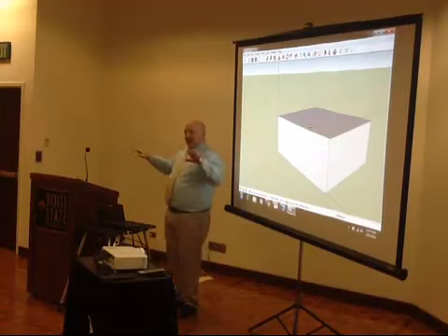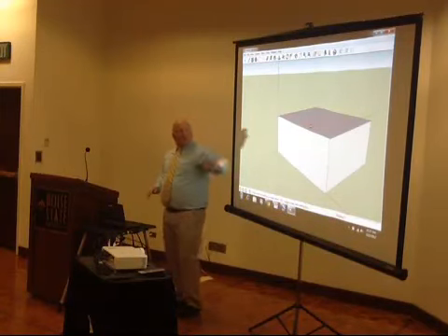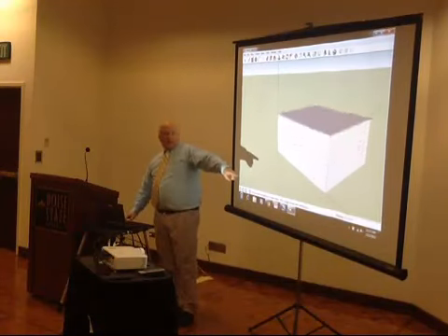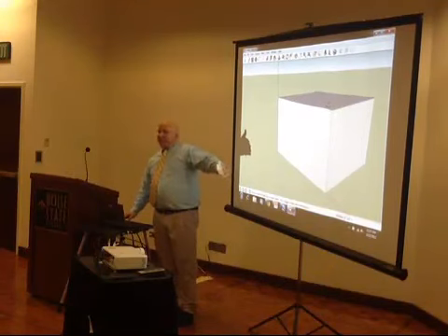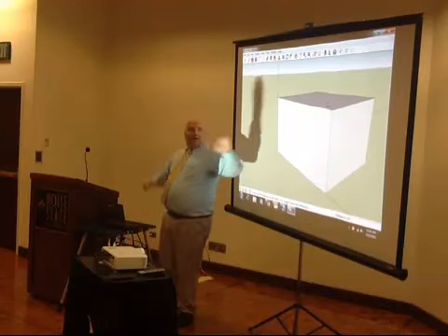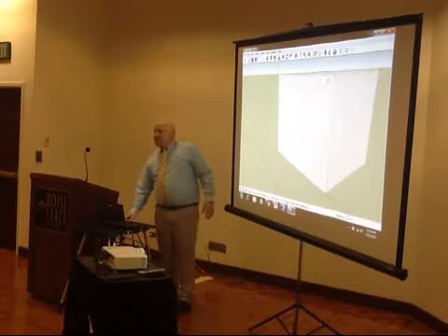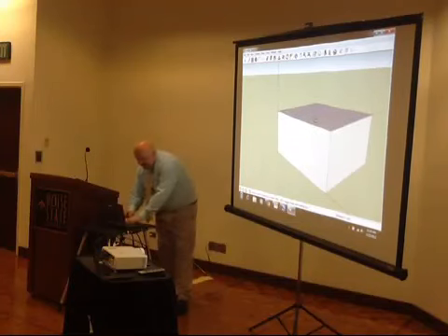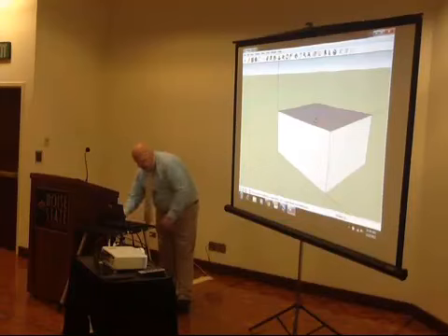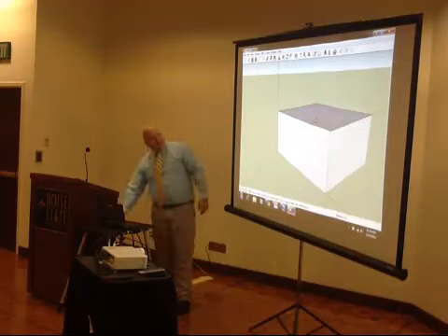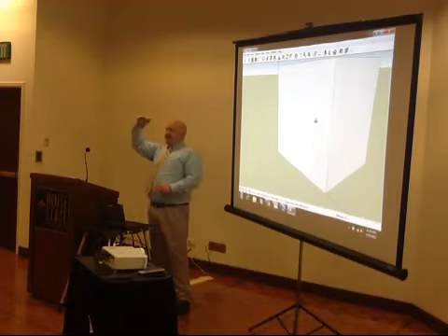One of the key features of Google SketchUp is that it's always paying attention to your keyboard. So what Eric's saying is if you look down in the lower right-hand corner, as I'm dragging up and down, it's saying, okay, now I'm at 6 feet 3/4 inches. But I want to be very precise. I haven't clicked yet to finish this drag. So what I can do is say 1, 5, and then hit the single quote mark for feet, and hit enter, and I've got 15 feet exactly.